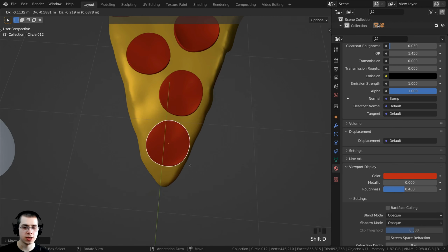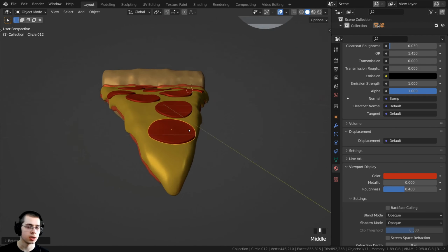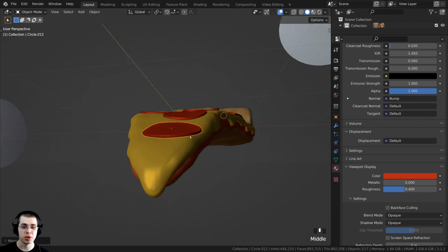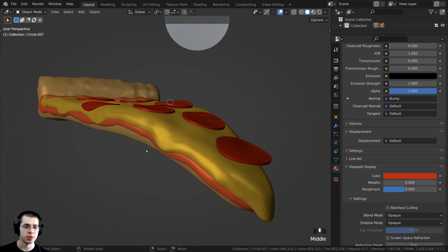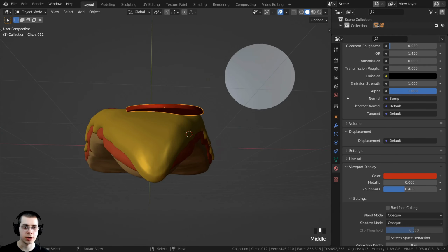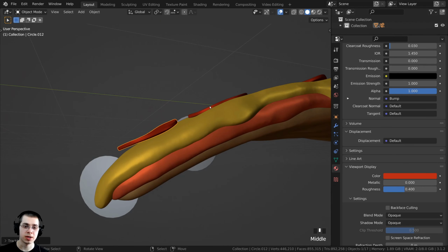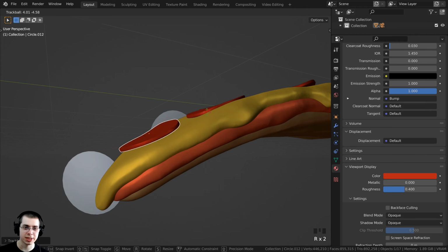So I'll press Shift D to duplicate and R to rotate, G to grab. And I want this one to be kind of falling down just like we did with this one. So I want this one to just be kind of falling down a little bit. So I'm going to double tap the R key, and double tapping the R key is going to activate the trackball rotation.